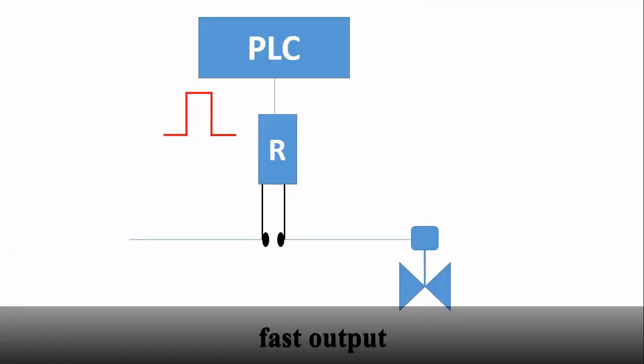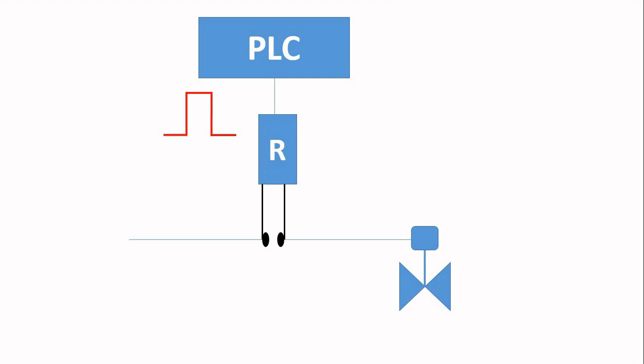So what is my problem? My problem is that I want to make sure that my relays will be closing and opening in the required timing. At the end, what I wanted to do is to make sure that this contact of my relay will send a pulse of 80 milliseconds to the solenoid, regardless of the PLC scanning time, the on to off to on time of my cards. At the end, I need to make sure that this goes between 80 and 200 milliseconds.